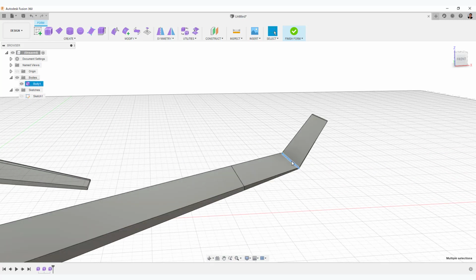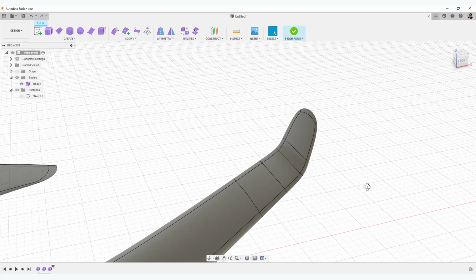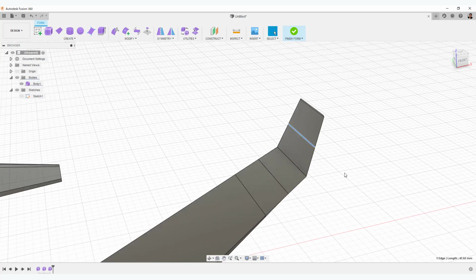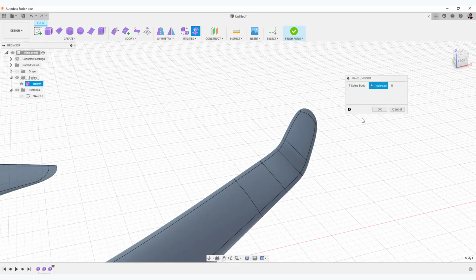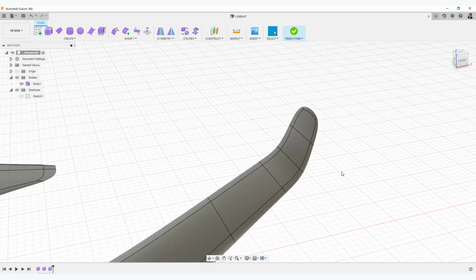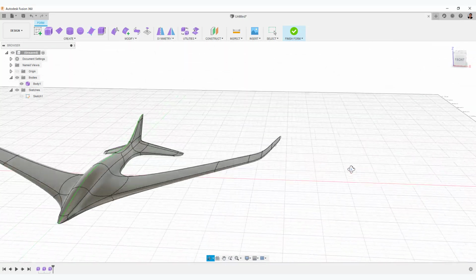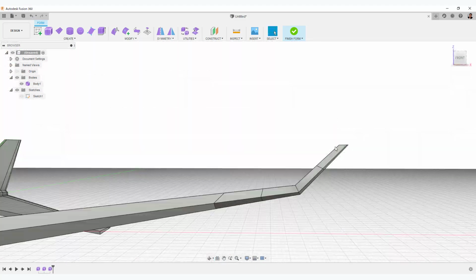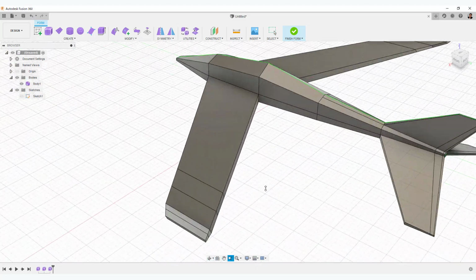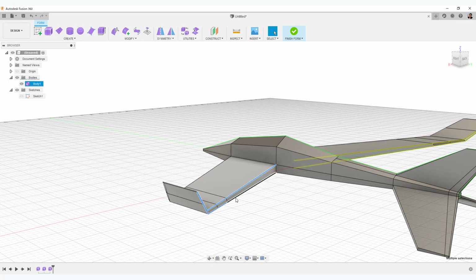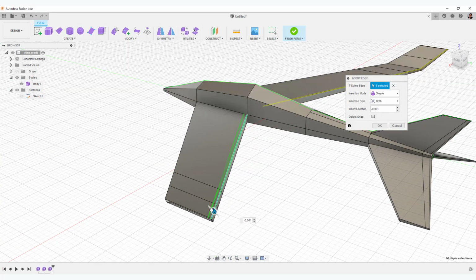Select this edge. Then select Insert Edges and choose both Insert in the Options menu. Fix tension bias with Make Uniform. Select this edge to adjust the curvature at the tip of the wing.